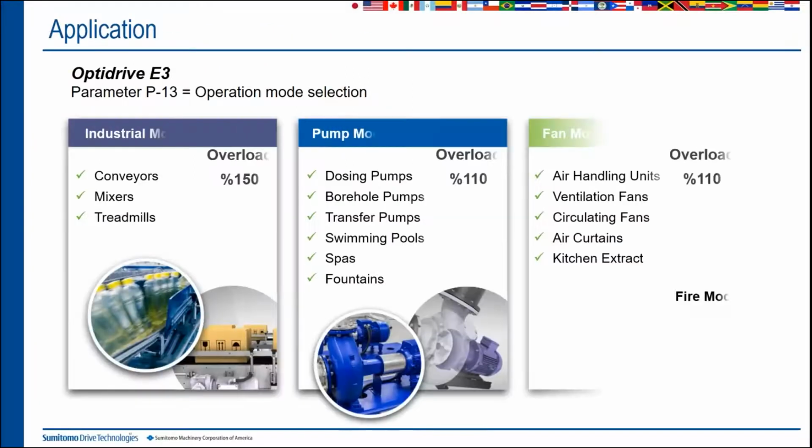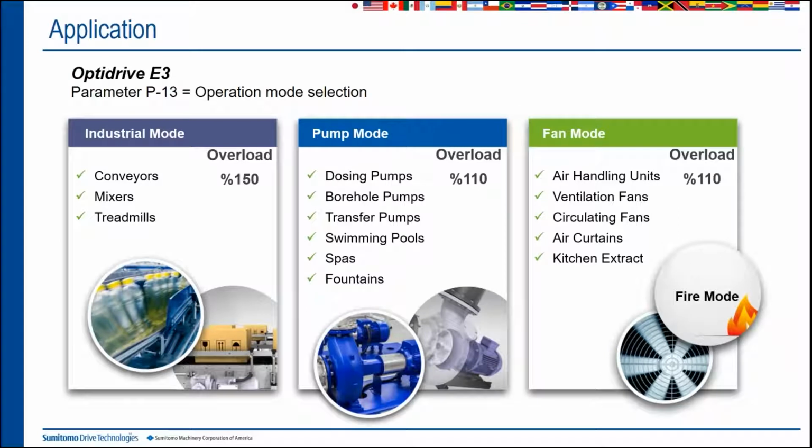There are some overload standards in almost all drive manufacturers. For Invertek drives, this will be, for example, for the E3 family. You can select the application for the E3. There's a macro configuration that you can use to say, okay, drive, you will be using your power for an industrial application.